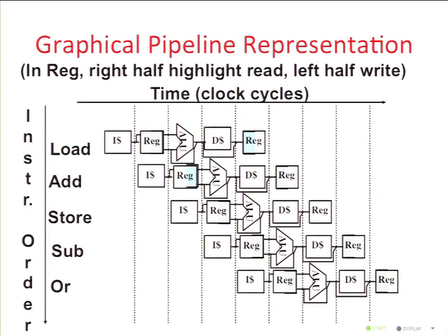And so you can see that at this stage, if we had these 5 instructions running, we have everything working at the same time. We have all 5 resources being used. Okay, and the other thing you see here is that there's a startup where you have to fill the pipeline, and in steady state, you want to be in this region as much as possible. You want to have as much going on as possible.